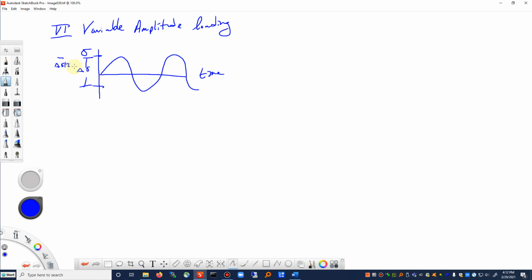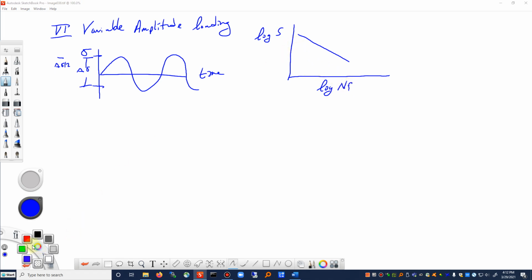We talk about mean stresses and all these different things, but basically we said when we tested at this constant amplitude, then we could create some sort of curve, either a stress life or strain life curve, or some kind of fracture mechanics type curve, where we would have maybe the log of whatever loading parameter, S or sigma or epsilon, and the log of the number of cycles or number of reversals to failure over here. And we can use this plot then to determine what our fatigue lives may be at places in between our data points by using an appropriate interpolation or best fit on our log-log type axes.